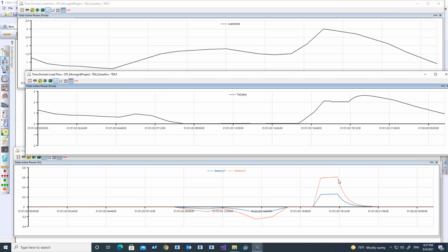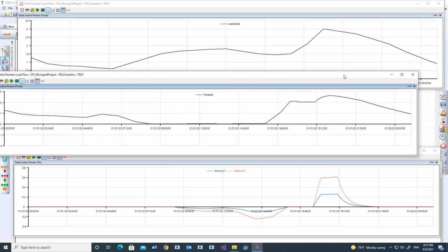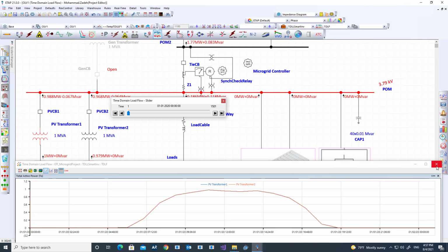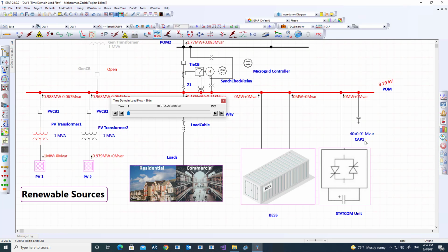That is commanding your battery to charge, to discharge, to do the peak shaving, to do the POI control. It can also do reactive power control, plan islanding, and all those kinds of things that I'm not going to go through at this moment. But if your purpose is to see the peak shaving analysis, if you are trying to do the battery sizing, if you are trying to do the reactive power sizing for a plant, for a microgrid, for a power plant, that's the tool that you need to use.